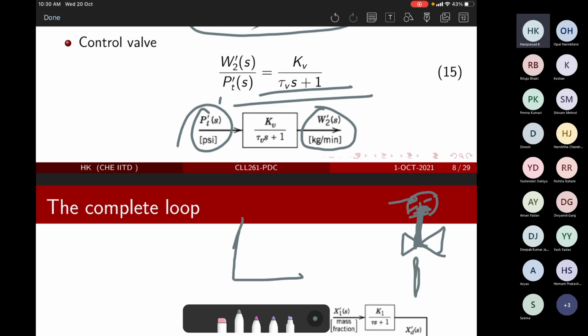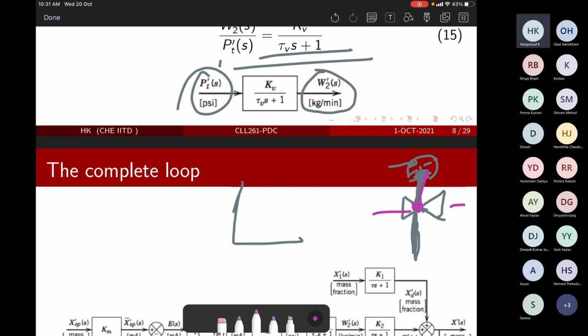The stem would go up and down, and basically the stem length is what controls the flow, because if it is fully up, there is no block. If it is fully up, this line is fully open. If it is fully plugged, there is no flow. So based on the pressure, you can see how this opens up, and you can see the stem position.